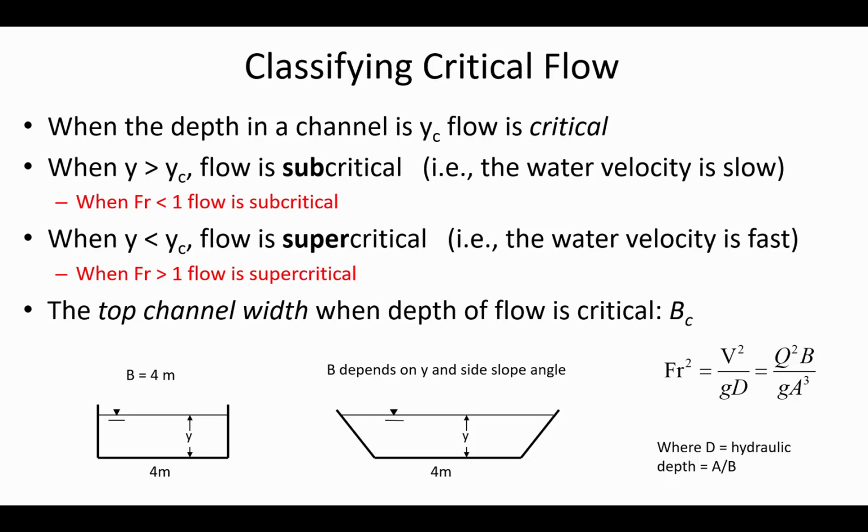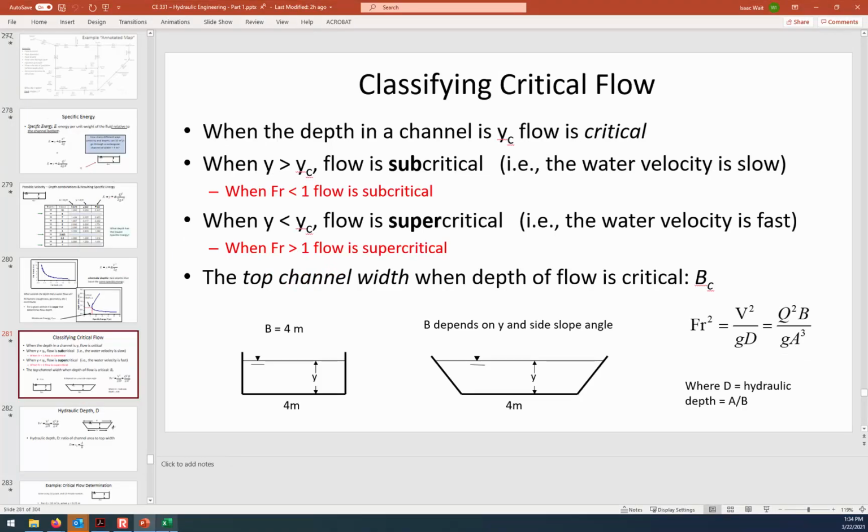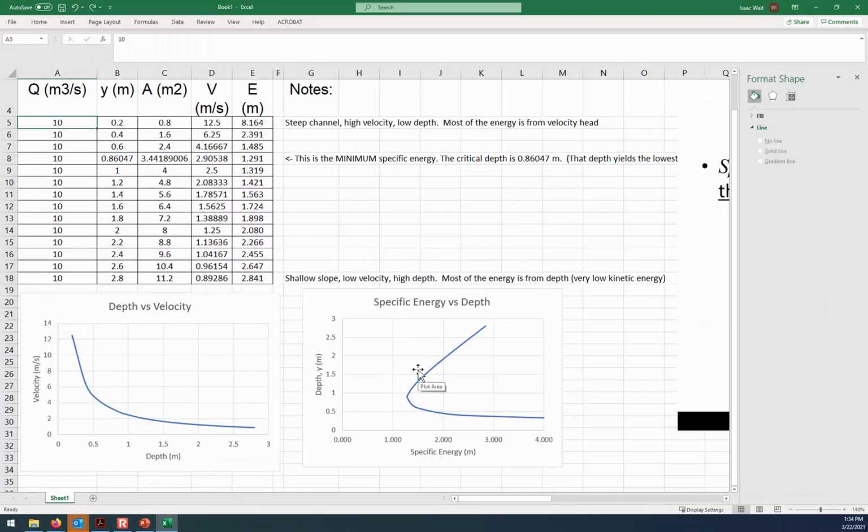All right, so this flow classification, you may wonder, is there a point to this? Is it just an academic discussion? Are we making these graphs just for no reason? The reason it is important is that whether the flow is supercritical or subcritical has a big effect on how the flow reacts to things like obstacles. Like if you drop a big rock into a channel, so now all of a sudden you've got a non-uniformity.